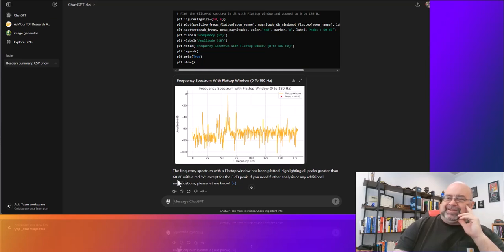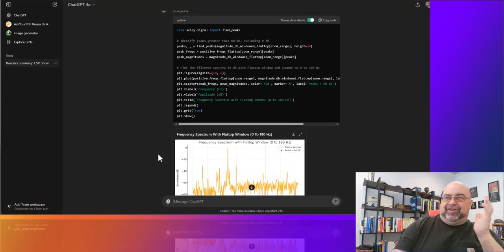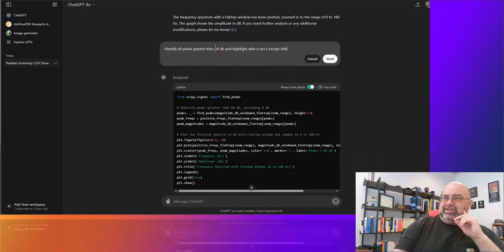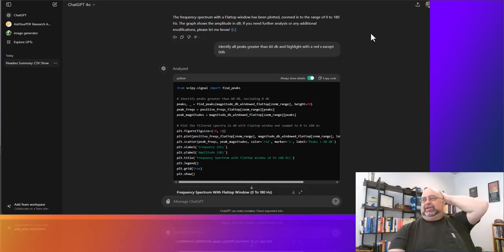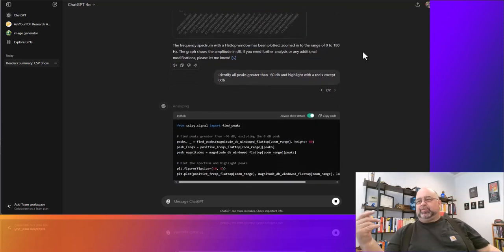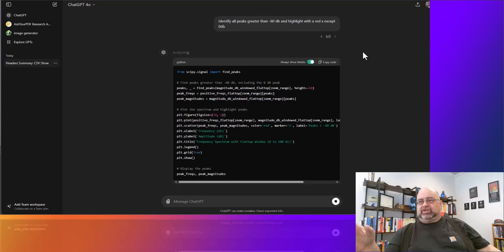Oh, notice I said greater than 60 dB. Error, big time. So let's go back here, and we're going to change this, and we're going to say greater than minus 60 dB, and redo it. So we'll let it fix itself. Now, if I had exported that, I could have gone in and just changed the dB value to what I wanted it to. Like it would have had it as 60 dB here. I would have called it the other. So now it's going to mark it up for me.